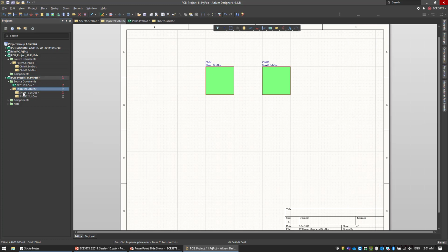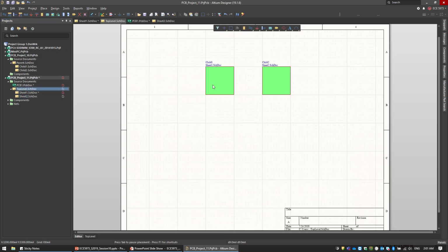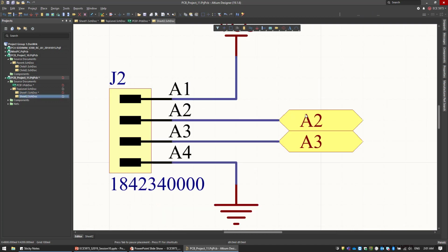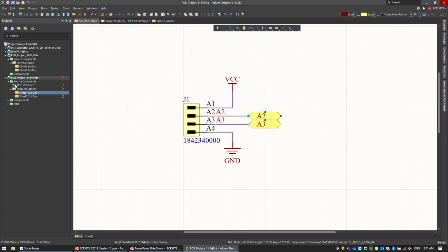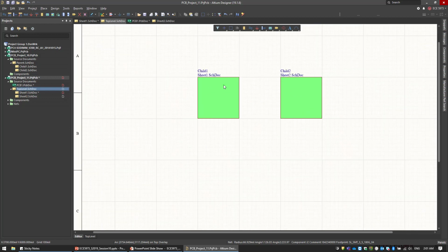You can see you have a top level. You know that this is a top level sheet, and this is sheet number 1, and this is sheet number 2, but you don't have any sheet entries in here. You don't have any boards, and basically the two sheets are connected directly with these ports, nothing else. And this architecture is still called flat. And what is the reason for having a top level sheet like that?